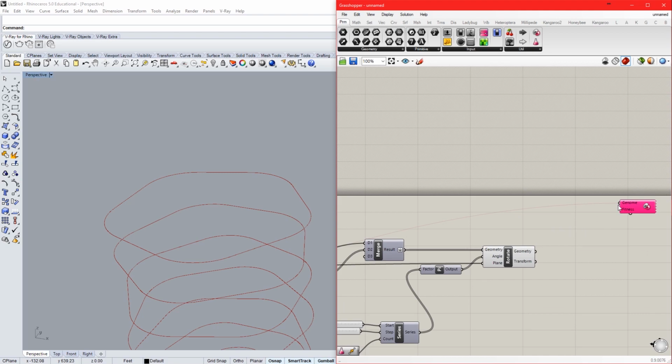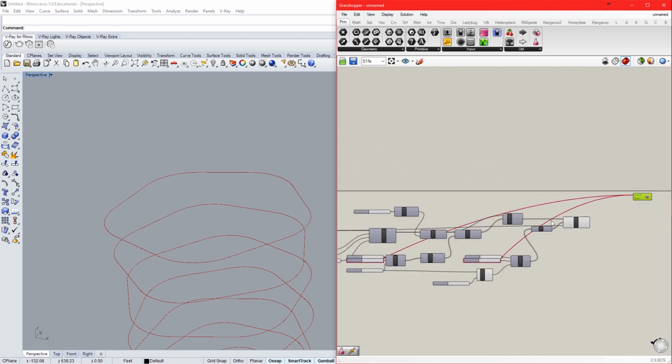Now you see that it replaced what I had plugged in for the rotation before. Whenever you're plugging in more than one input, merging wires together in an input or an output, you want to hold shift. So for genome to have more than one value, I hold shift, and you see that plus sign pop up next to the mouse. I bring it into this number slider again. All right, now I click on Galapagos and make sure I have 2 values that I'm testing with.